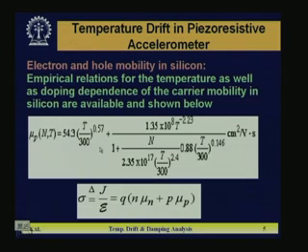Since it is an empirical relation, you will see the values are not closed form values, which is 2.35 here, 300, 0.88 here, 135. You may ask, how did you get those parameters? Any empirical relation will not follow a regular method by which you get a closed form relation mathematically. Some of the numerical values you have to adjust to get agreement with the experimental results. That is why those are known as empirical relations. Similarly, you can get it for the hole mobility or the electron mobility.